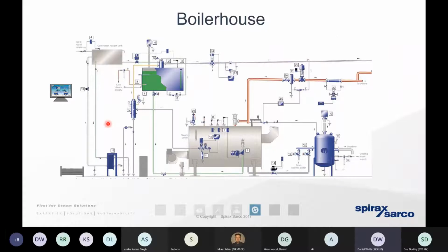from an energy perspective, that steam is being generated reliably, that the mass of steam is generated as and when the process requires it, that the steam is generated at an excellent condition. So it's as dry as it possibly can be to minimize the risk of that erosion, corrosion and water hammer. But most importantly of all, to ensure that that steam is being generated safely.